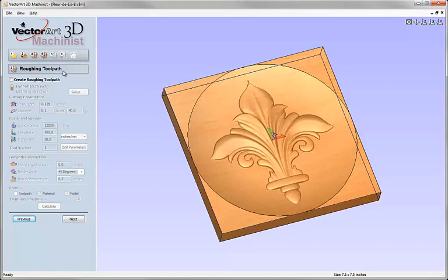In the case of a dished model though, it's a little bit unusual in that the tool, the finishing tool, is going to start on the edge and then work its way across the model. So the first cut it makes is very, very shallow and therefore doesn't provide a lot of stress for the tool. After that, it's moving over a very small distance each time it makes a new cut, and so the tool is never overstressed. So in a job like this, where we don't have a particularly deep dished model, it's not particularly large, we can probably avoid the roughing stage.